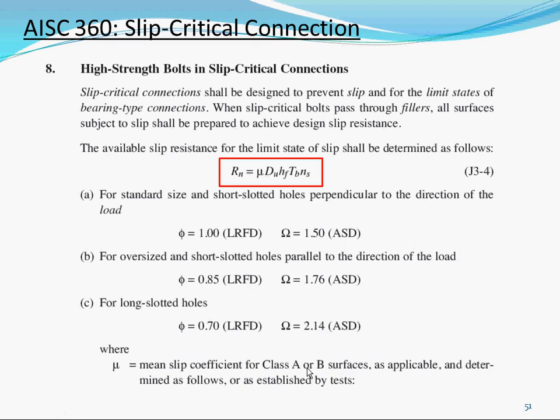So if you do consider a slip critical, there are some requirements for the preparation of the surfaces. You have to blast it clean, or you have to make sure that you get to a certain friction. For us, we didn't test it that way, but we did have a pretension bolt. So ours, the only thing needed is pretension, and also we tested as regular steel condition. We didn't paint it or anything when we were doing testing. So we wanted to match the testing condition, which is like this. We paint everything around except the area that's contacting the steel. We leave it because that's how we test it. If we test it painted next, then we might modify the arc of protection a little bit, and maybe modify the strength a little bit. But at this time, when you see the actual finished link, this side is not painted.